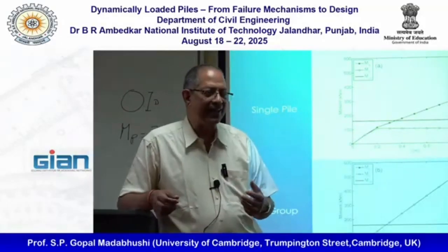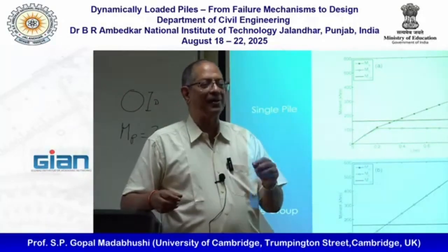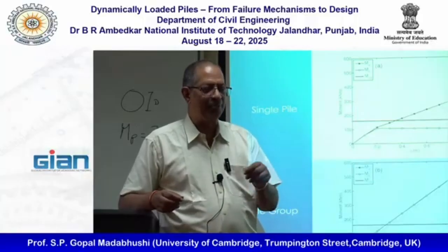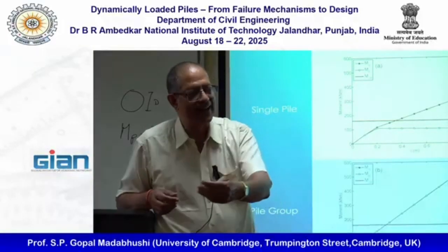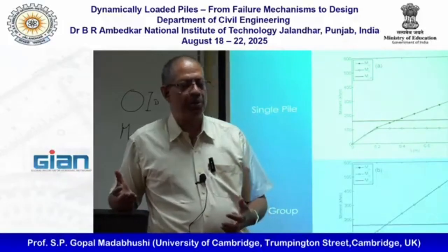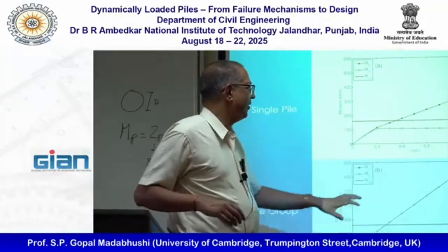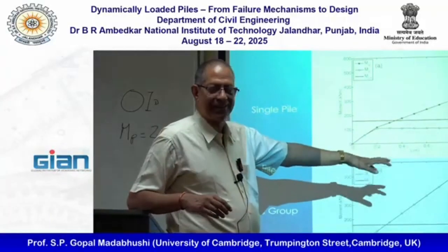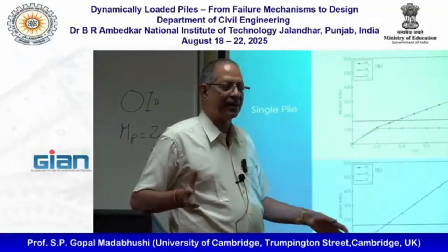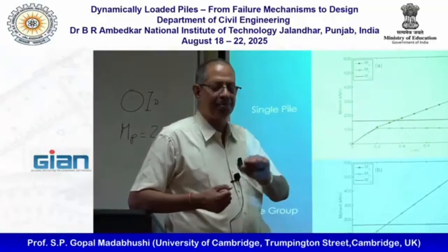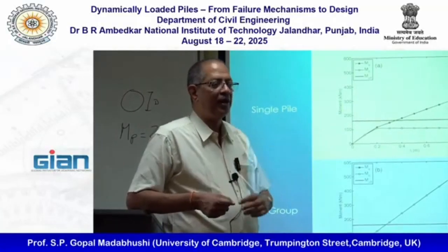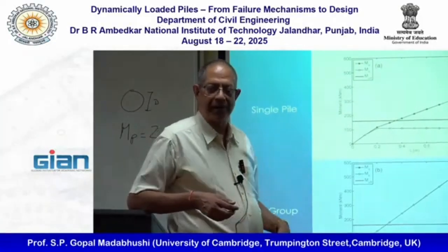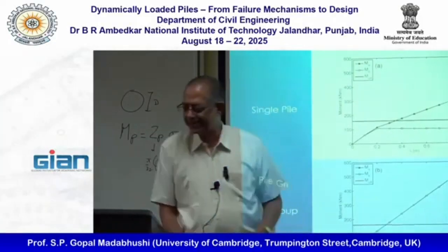So the worry is that although I have this plastic moment capacity, the more deflection I give, the worse it gets, the more the P-delta moment will become. Therefore, that hasn't percolated to piles, and nobody has done enough research to say, after the plastic hinge is formed, how much load, how long before I will completely collapse the pile. So there are reasons for it.